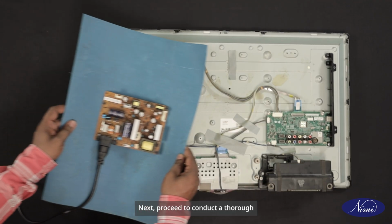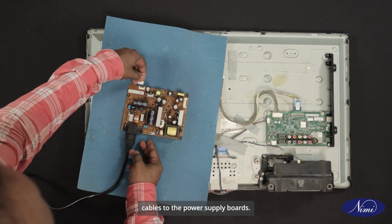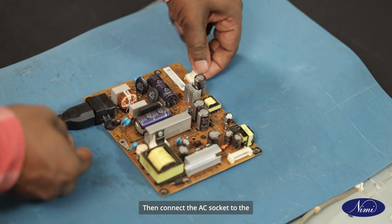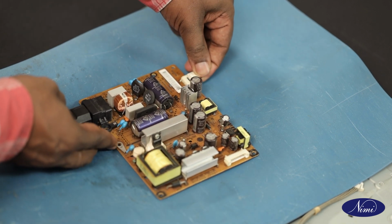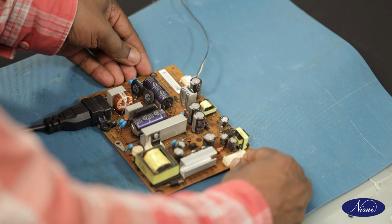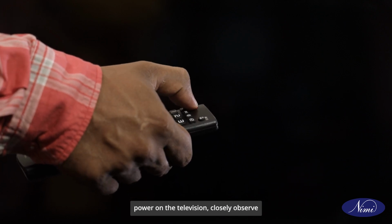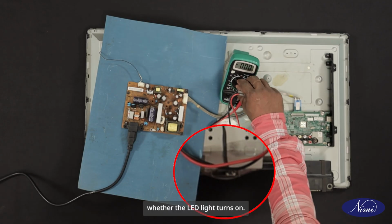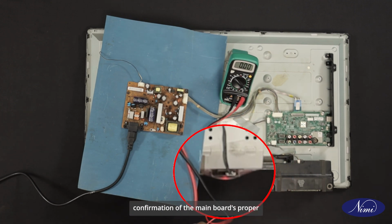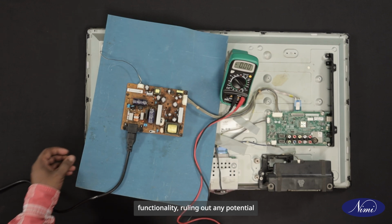Next, proceed to conduct a thorough inspection of the main board. Connect the main board and backlight cables to the power supply boards. Then connect the AC socket to the power supply and switch it on. Next, using a TV remote controller to power on the television, closely observe whether the LED light turns on. The activation of the LED serves as a confirmation of the main board's proper functionality, ruling out any potential power-related issues.